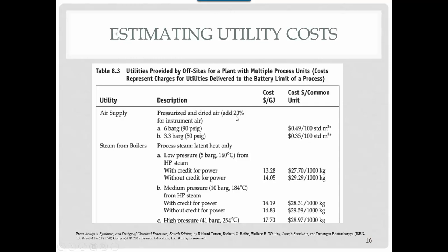Okay? Now, air supply, we didn't actually talk about that, but in plants, the legacy control equipment is very frequently going to have pneumatic systems in it. And you may need it to drive a lot of other systems. So you will have a high pressure air supply. Okay? Whatever air supply you need, it's not really providing energy. You're just needing to provide so much volume of air. And so these are your cost values based on volume.